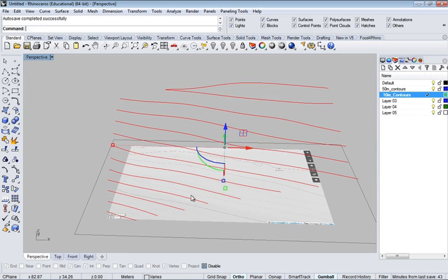So having that rectangle, using that rectangle, I wasn't able to replicate what you guys did. So if I get rid of that rectangle and just use the contours, then it actually creates a surface that expands past those contours, and then I can use that rectangle to trim it back down to the way I want. So what I just did is I locked that down so that's not going to be selectable.